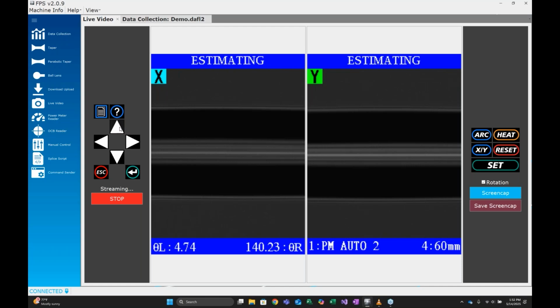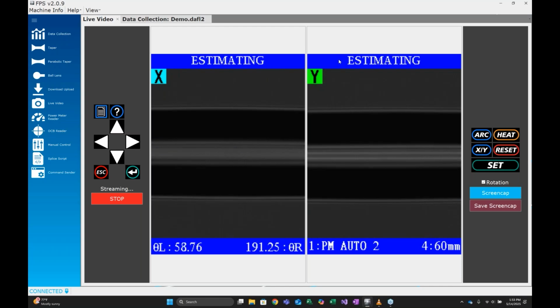You toggle between motor drive and LED adjustment using the menu key in the end view alignment mode. You just hit the menu key and the splicer will move to adjusting the end view LED brightness, and it'll usually pop up on your Y camera side as text showing the LED brightness in bits. It is a digital machine, so digitally, the machine understands the LED brightness in bits, and the maximum brightness is 1060 bits all the way down to 0. And that's adjustable on either side.